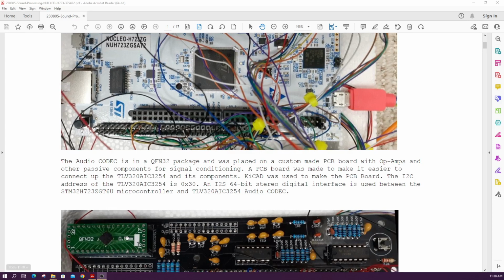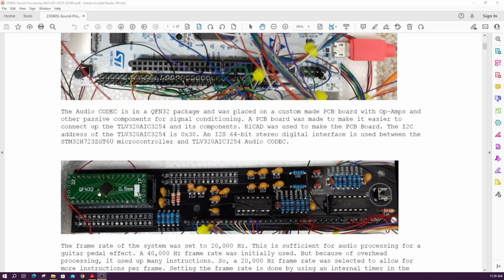to this audio codec. Now these audio codecs are very common. Hardware like, I guess, the cell phone technology probably really pushed this, because every cell phone has at least one of these in it to get the audio to work. So there's a couple of op amps, two quad op amps, and some of these are all 100K resistors and some capacitors. A lot of this was taken from the data sheet for this audio codec. So I tried to use the designs that were already suggested by the data sheet, and then some of this